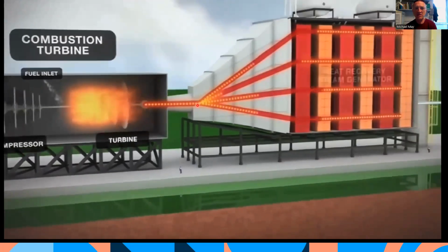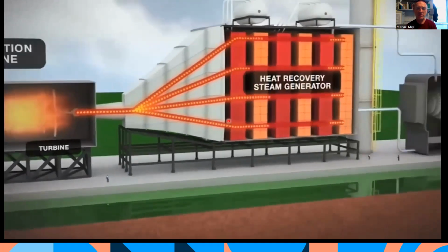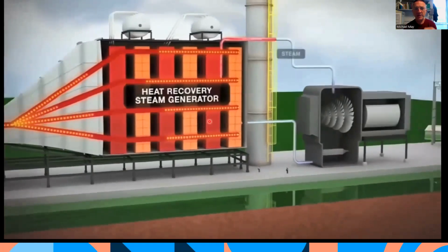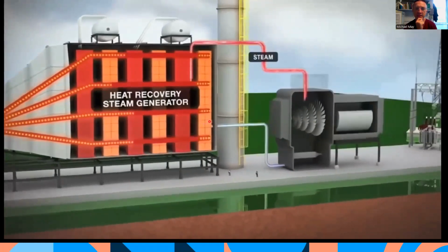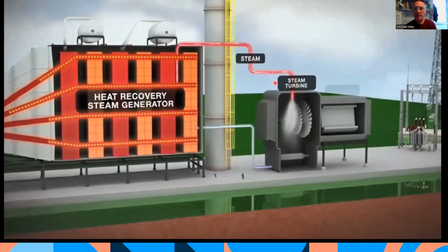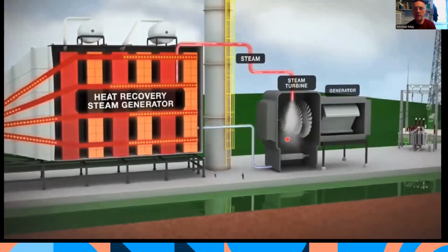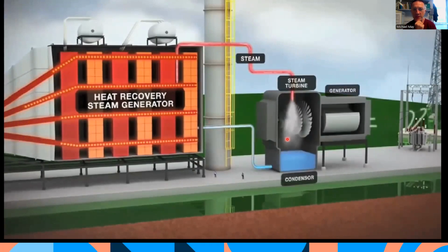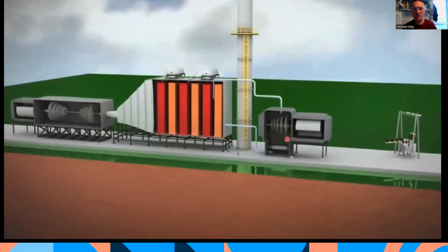And then the exhaust gases are put through a diffuser to reduce their speed and increase their pressure. That will help generate steam in the boiler, and the steam comes out and it drives the turbine. So it's a combined cycle gas turbine system, and it's the type of system that would be used down in Poolbeg, which provides most of the energy to the Dublin region.